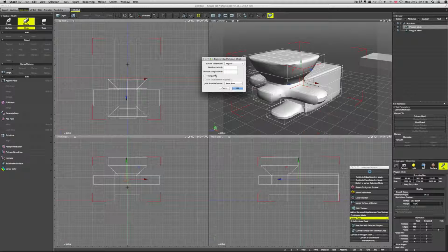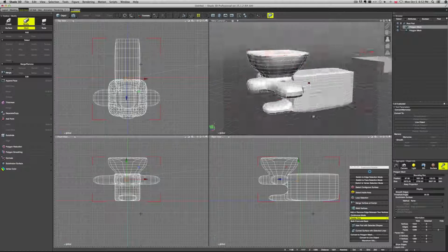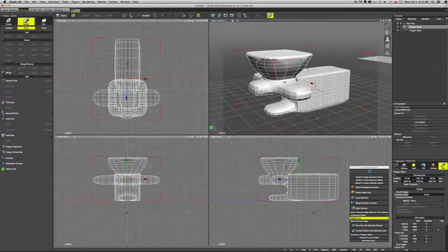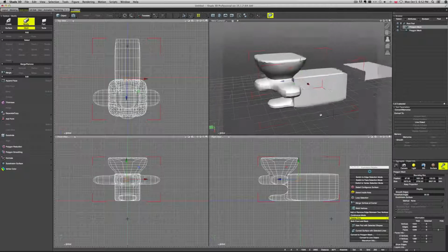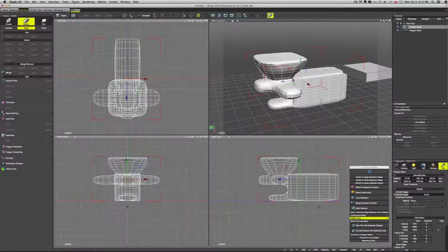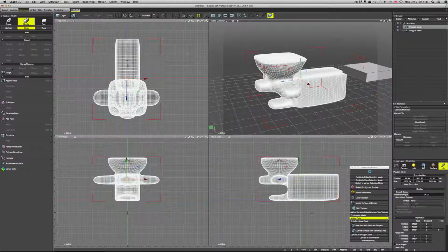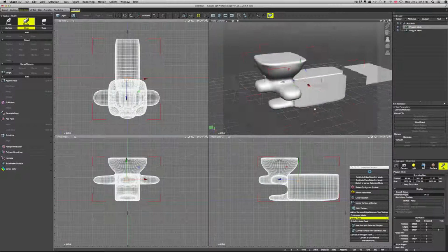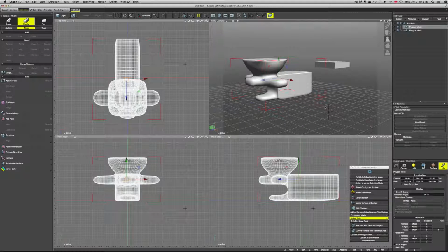And then if you want it subdivided this way, you convert it to mesh, pick the level of subdivision and confirm, and it subdivides it. Now it's subdivided, it's not a preview anymore, it's actually the geometry. And you can of course keep going further and further. You can again subdivide this already subdivided one and turn it into another even denser mesh. So you can make it smoother and smoother. Of course, you have to be mindful of the number of polygons.